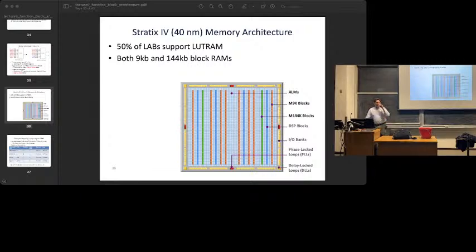Yeah, it's hard to give a perfect answer. So if you were close to the capacity of this, and close probably means, you know, even a half, a quarter, then probably you're better off using the bigger RAM. It's going to be more efficient than building it out of a bunch of LUT RAMs. So from a silicon area point of view, that's probably around where the trade-off is. Even if you only use about maybe a quarter of that, probably still a better option. Once you get down to I'm only using an eighth or a tenth, the LUT RAM probably becomes a better option.